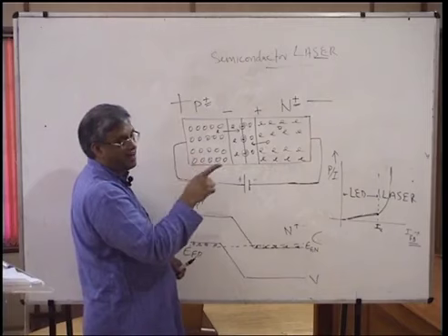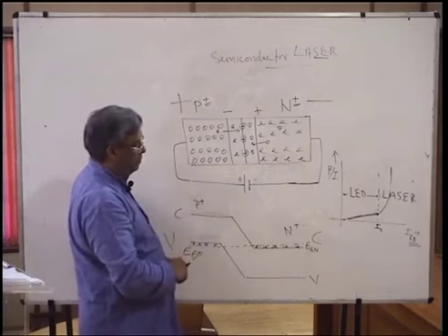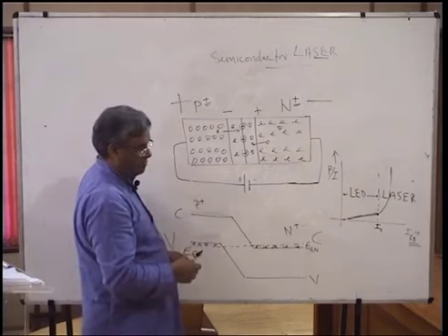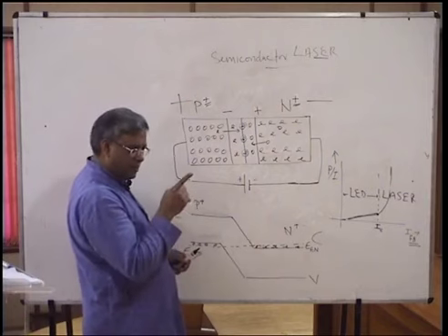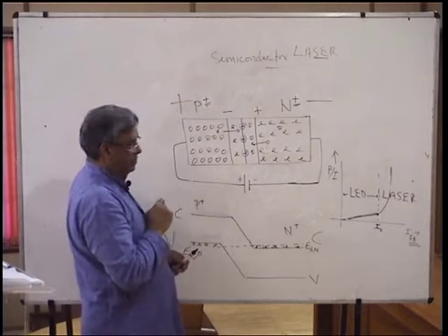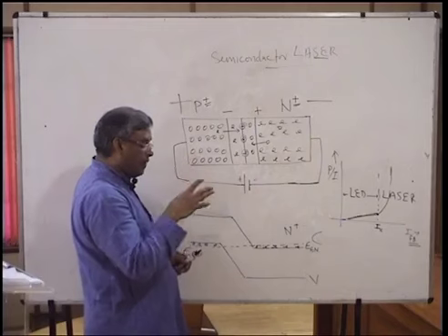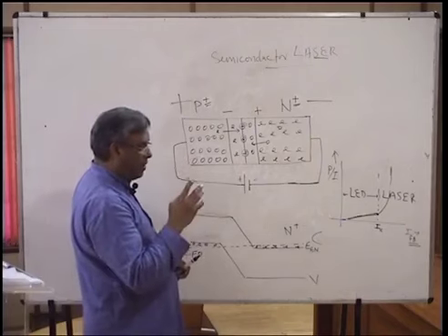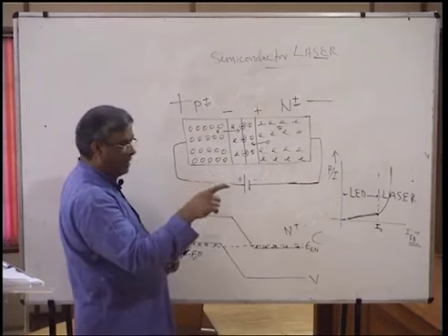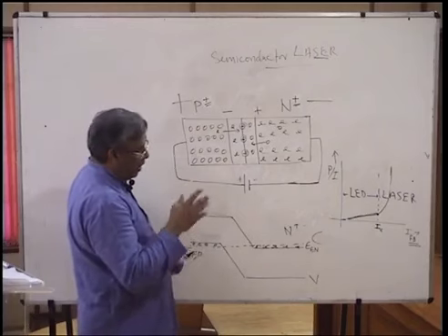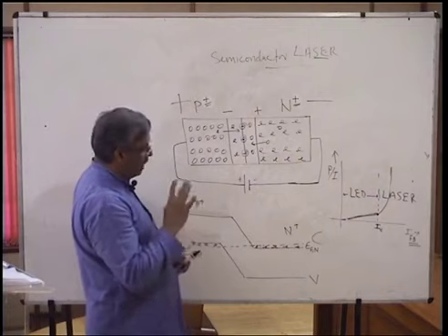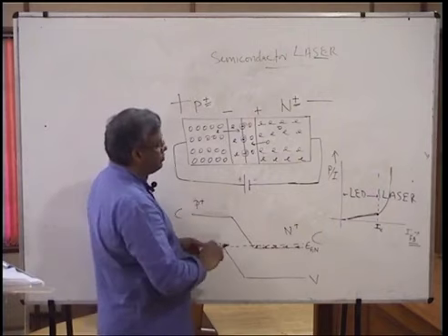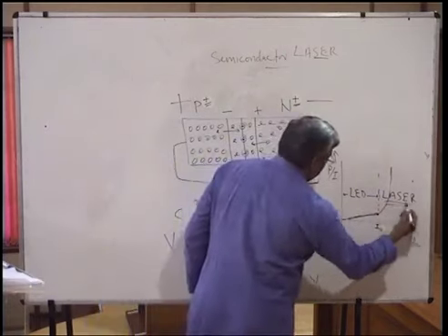It's a very brilliant red color, which I've seen in the lab. LED is not that brilliant. So brilliance means monochromatic. That particular light is highly monochromatic. So you have a highly monochromatic, highly temporally coherent, and highly directional, highly spatially coherent light, which we call semiconductor